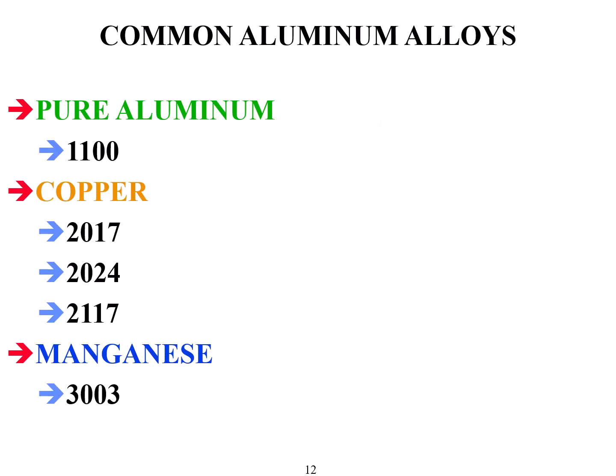Here is a list of common aluminum designations that's used in aviation. 1100 is pure aluminum, commercially pure aluminum. It is generally not used unless it is light trim work. No structural application comes to mind when using an 1100 aluminum.